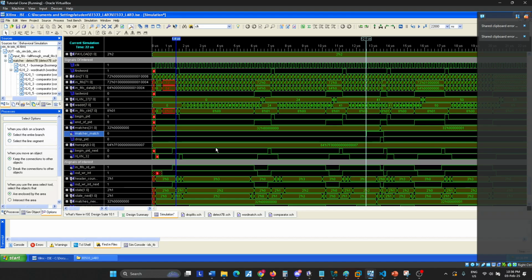This pattern match signal is going to remain 1 for these 3 cycles, as we said before, because that is how many cycles it will take for the new packet to come in. So it needs to stay high for that particular duration when it finds the malicious packet. The drop packet signal basically will tell the circuit to drop that particular malicious packet and update the pointer.